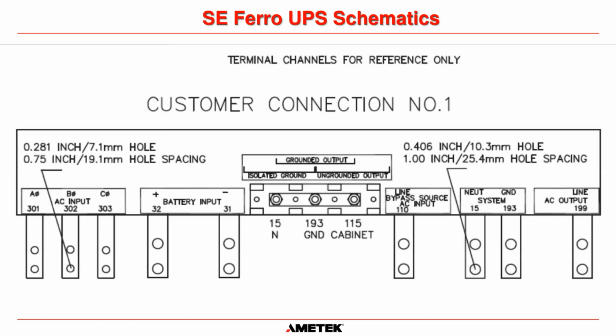And you can see, once again, we've got A phase, B phase, and C phase. And you can see at the top here what the hole sizing is. And because there are two holes, we also tell you what the gap between the two holes is, so you can use two hole lugs if that's what you want to do. So on this one here, it's 3/4 of an inch spacing for the hole spaces. Okay. And the hole size is 0.281 inch. So you can size your lugs according to that spacing. Now that's for the AC input to the charger.